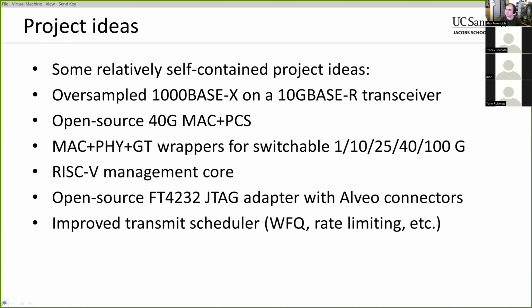I think we looked into this a while ago, how you could do debug access to RISC-V cores in the design somehow over PCI Express. There's a couple of different potential routes that could be taken for that. And that would mean you can use GDB single-step debugging type stuff, and you can very easily update the code on there.